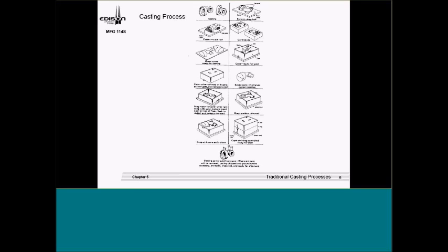And then we'll start ramming, which we actually have some rammers that literally hit the sand as it comes through. And as you can see over here, what we're doing is our sprue and our riser, and we actually have a pipe that we use for that. We don't do any core prints.